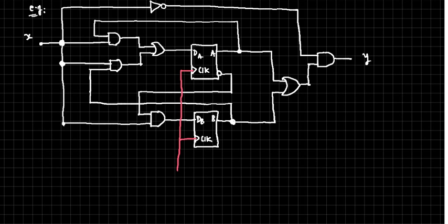So can you tell me how many inputs are there? Step 1 is to find how many inputs there are. Only one. Tell me how many present states there would be. Just because two flip-flops are involved, two storage elements, there are two state bits. How many combinations? 8 combinations. How many outputs are there? Only one. Draw the characteristic table, find the behavior, and also draw the transition diagram. Do that, quick.